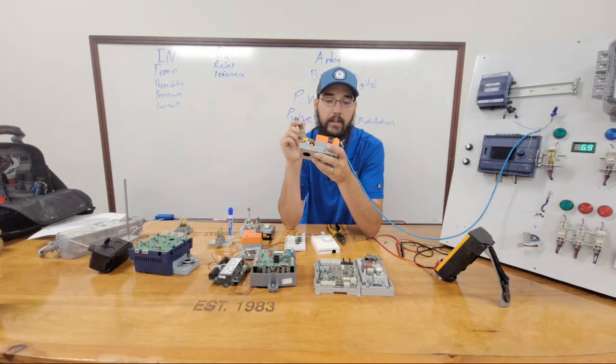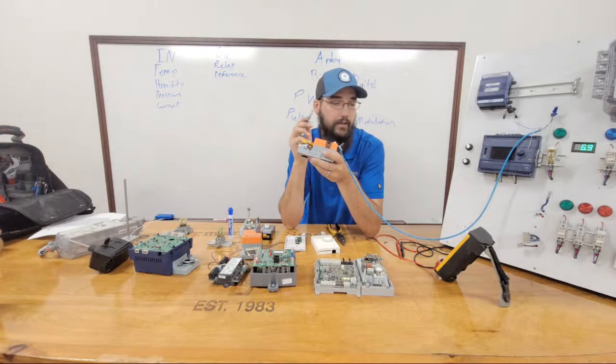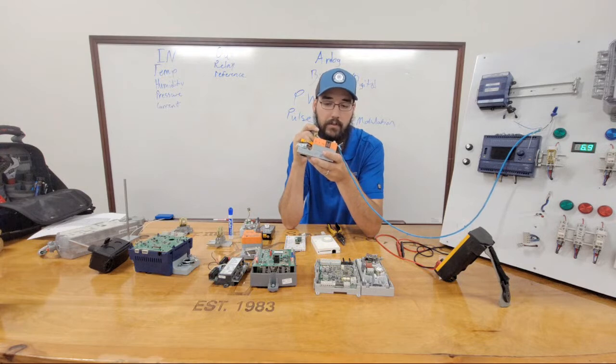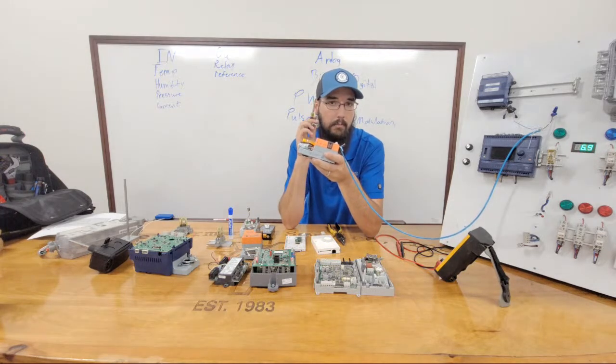So it's going to keep spinning until it registers that it has hit that potentiometer point. So just because you hear that motor start turning, my point is, don't just assume that the actuator is functioning. Make sure you watch this gear assembly and that it actually rotates.